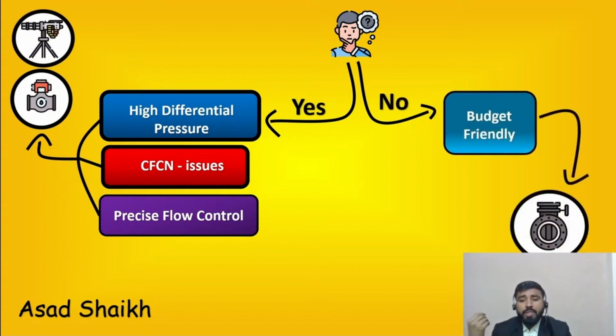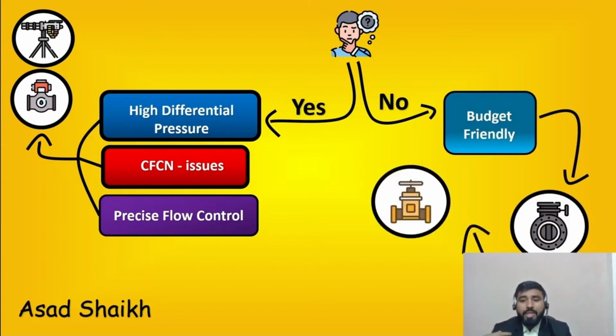For example, you will first try a butterfly valve. If butterfly doesn't work, then maybe you can look at tougher applications, for example a segmented ball or plug valve, which can be in the middle. So basically the best overall for applications is the globe, but it is the costliest. In the center you have ball or segmented plug valve, and finally you have the butterfly valve, which is the most cost effective option.